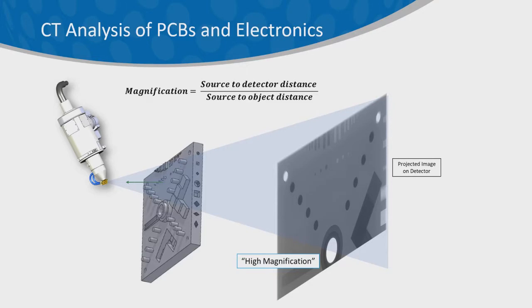This can limit us, because you'll notice that in order to obtain a slightly higher resolution, we have to focus on a smaller area. So we have this trade-off between field of view and resolution that we really have to abide by. That's at the core of X-ray imaging. As you can see, that can be a challenge with some of these large motherboards and server boards. If we have a large 16-inch board and we want very high micron-level accuracy on it, you can see some of the trade-offs we have to make, maybe looking at a smaller area, maybe getting a bigger, higher resolution detector. Those are some of the trade-offs that we fight in CT. We'll talk a little more about that.